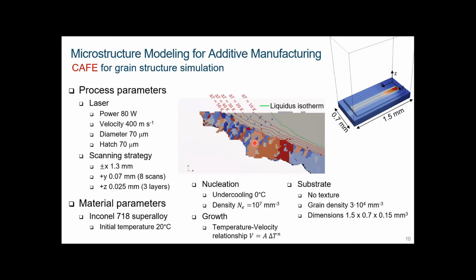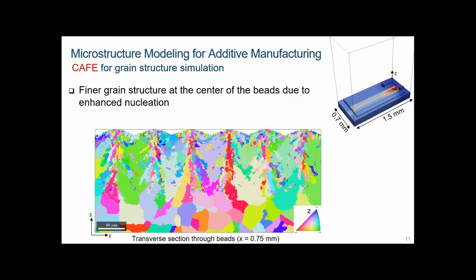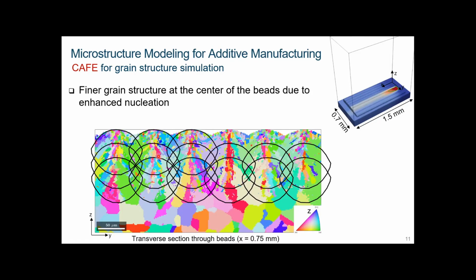Now this was one of the very first simulations that was done by a PhD student, Théophile Camus. So it's relatively coarse. You will see at the bottom you have this equiaxed structure. So we melted the structure by moving this bead shape and remelted shape with the temperature field, and we could compute progressively and grow the columnar structure and equiaxed structure.